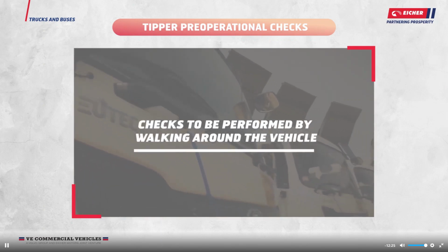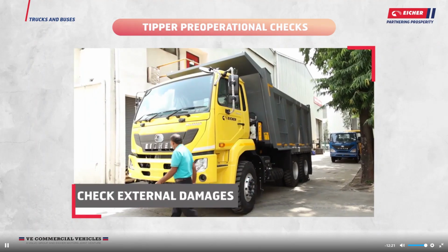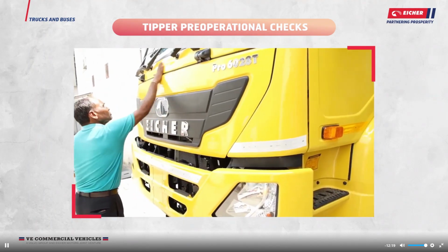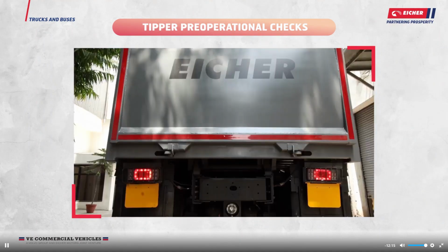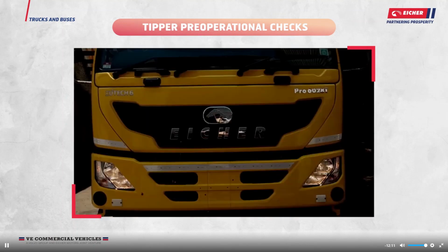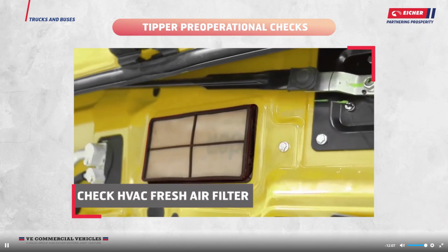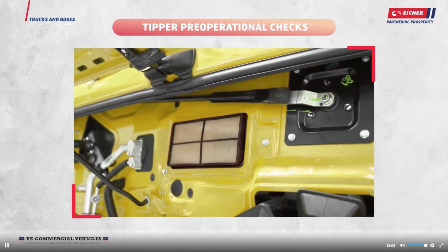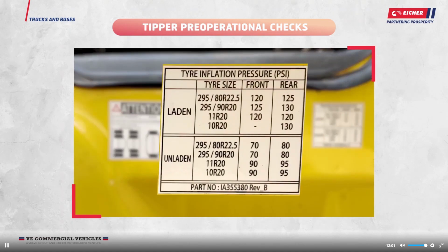Checks to be performed by walking around the vehicle. Check for any external damages, dents, scratches on the vehicle. Check for functioning of headlamp, brake lamp, reverse lamp and indicators. Check and clean the HVAC fresh air filter. Check and correct the tire pressure as recommended.